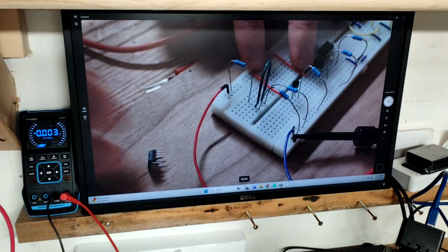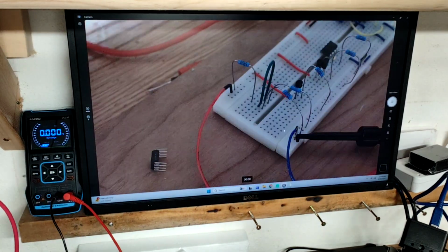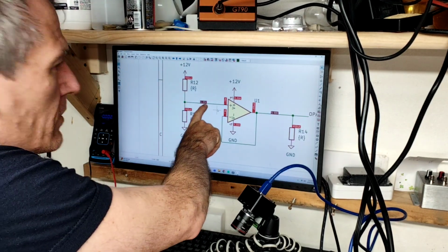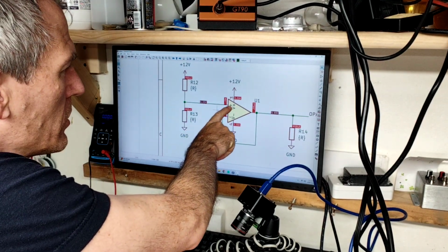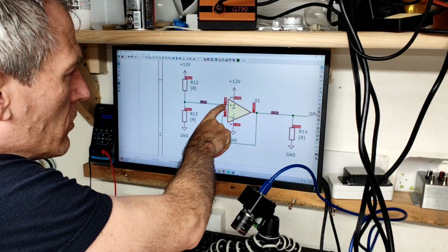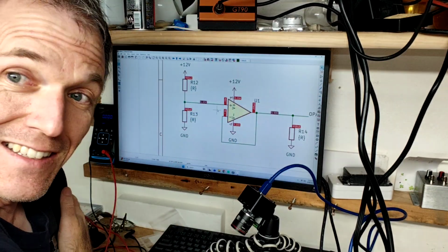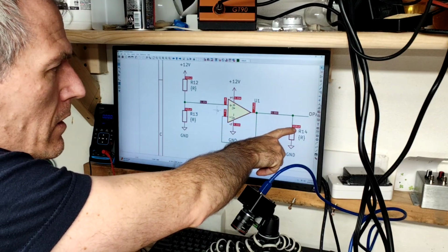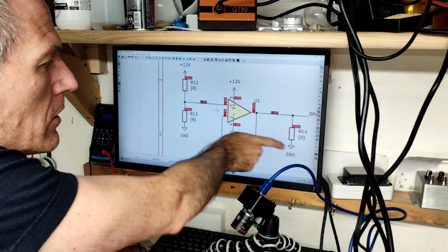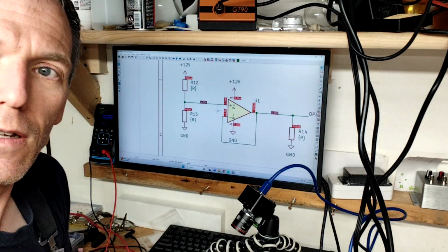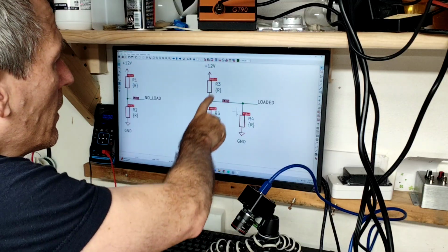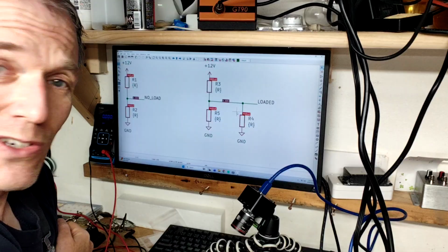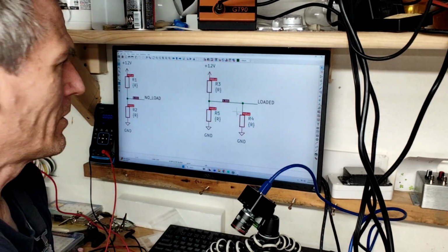So what a buffer does is it allows us to keep the same voltage but amplify the current. So we have 6 volts here with this buffer. How much is going into this op-amp? 0.00 amps. This is an ideal simulation. And what do we have coming out? On this other side, we have almost 600 microamps going through there to ground. In our circuit with the load, we have a huge amount of current going through both of these resistors. It's really just 2 resistors in parallel, so it pulls this way down.